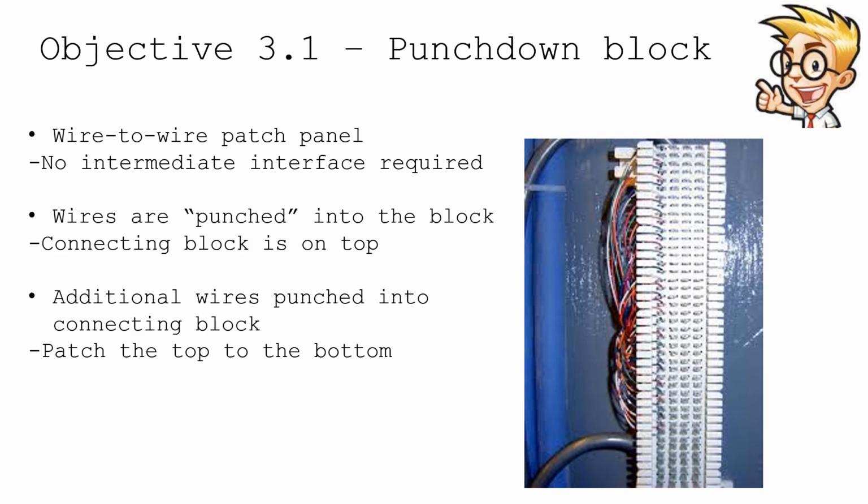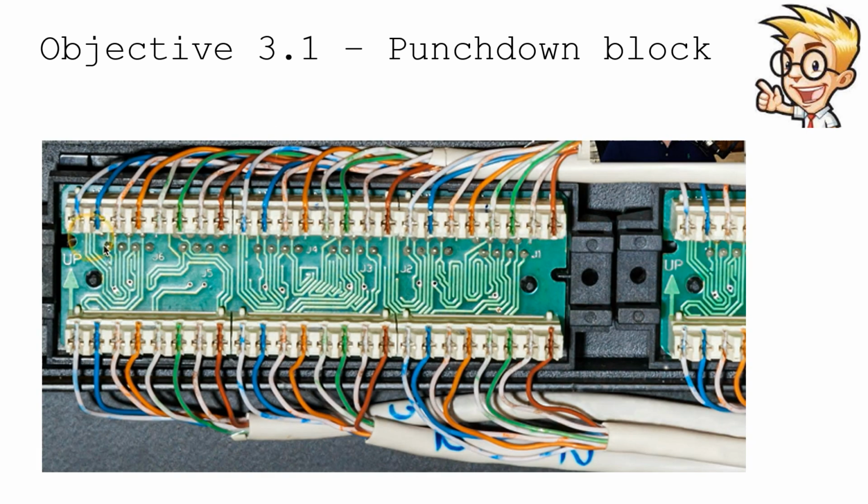Look at the wires that are punched down. They were punched down with the tool. You can also see that the connectors push through the insulation of these wires, and they make contact with copper that's on the inside. Here's another picture. Take a look at these punch downs. This is on a wiring block, and this has a punch down on each side. And if you were to see the other side of the block, there would be RJ45 connectors to complete the circuit.